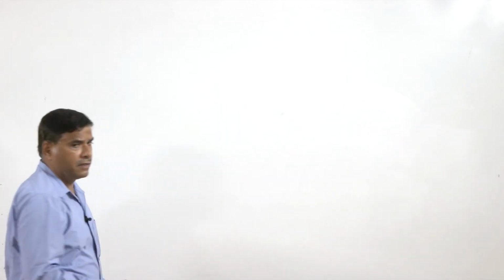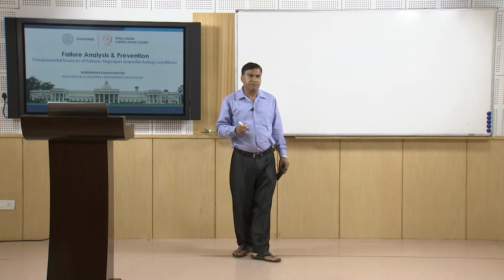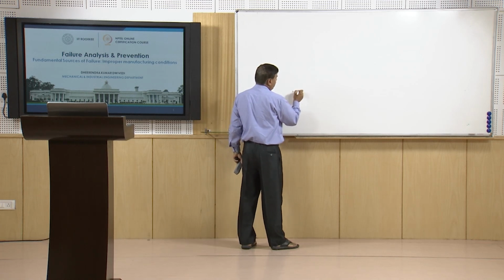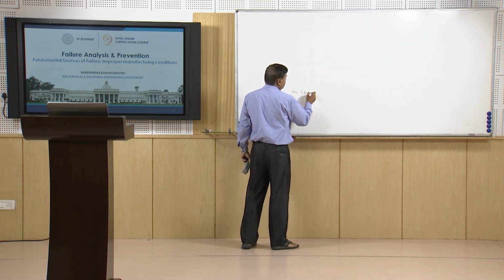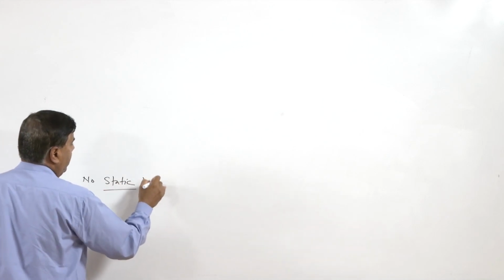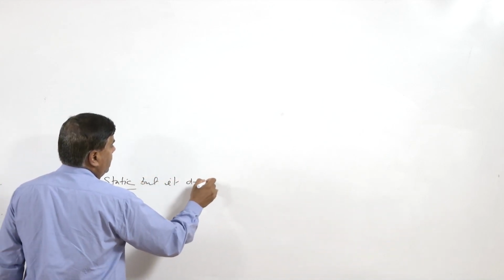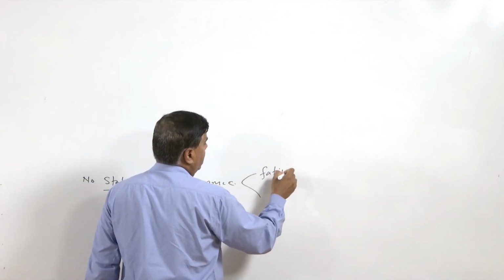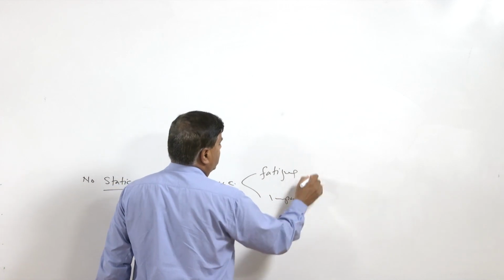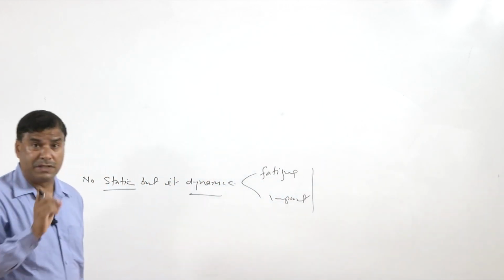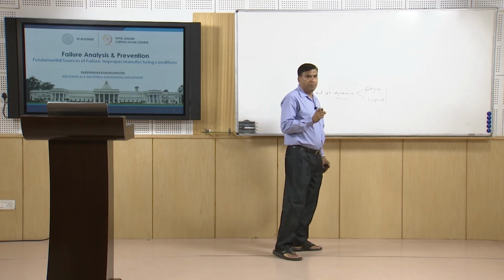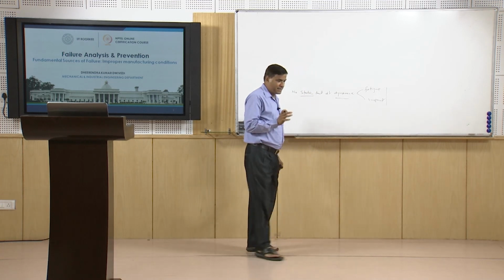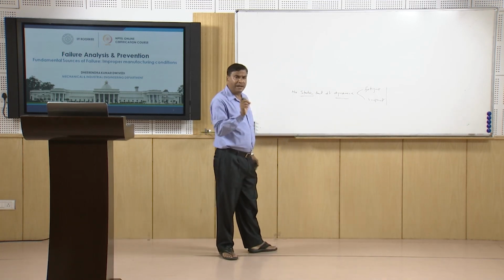And we know that nucleation and growth becomes easier and faster, especially if the load is not static, but dynamic. Like the load is fluctuating, say fatigue loading or impact load conditions, such kind of stress raisers become more harmful, because the time available is not much for the stresses to get relaxed due to localized yielding.